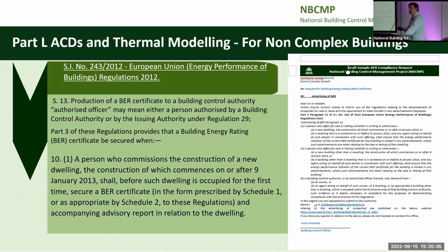So when you get a CCC, you submit a CCC for a new building before it can be opened or occupied. So a building control officer will need to see the BER and the CCC at the same time to say that that building can be opened and occupied, because he has the function for both regulations.